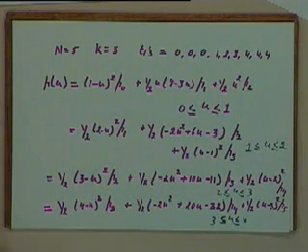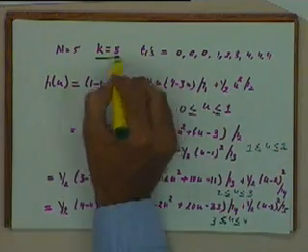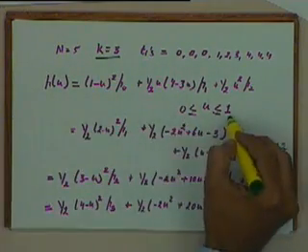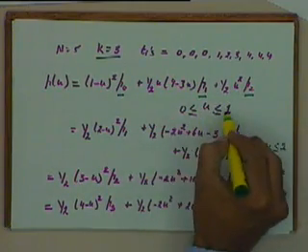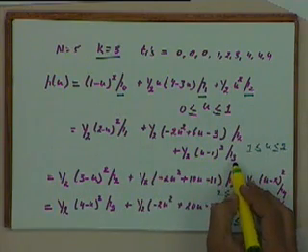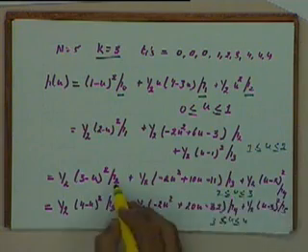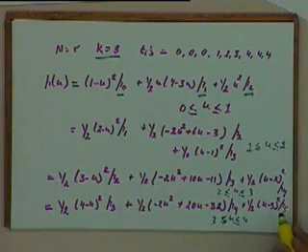Now again, as we should have expected, since k is equal to 3, in any range of the curve we have 3 points which are effective. P0, P1 and P2 are effective when u is between 0 and 1. When u is between 1 and 2, P1, P2 and P3 are effective. Between 2 and 3, P2, P3 and P4 are effective. And between 3 and 4, P3, P4 and P5 are effective.